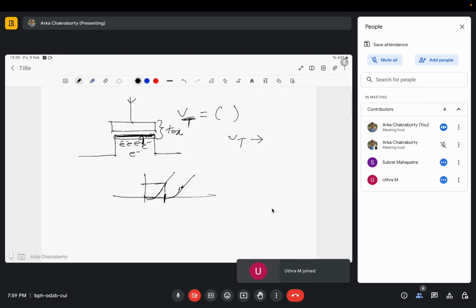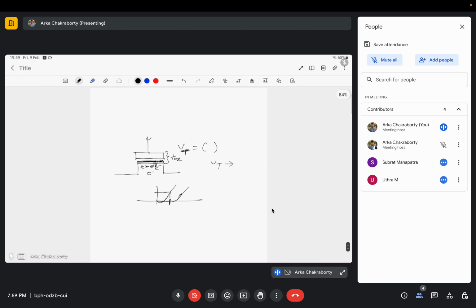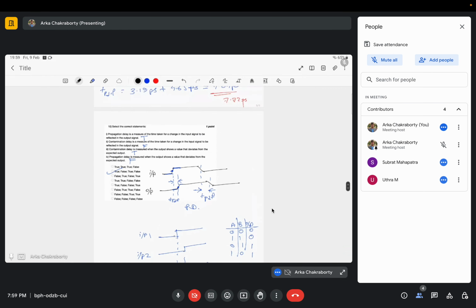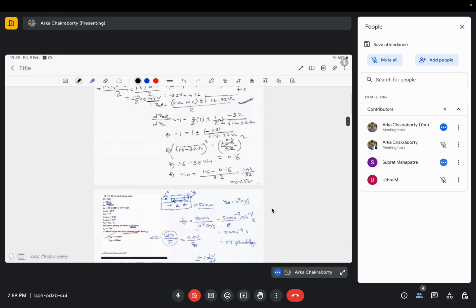Lots of research is going on here, and this is a very interesting field to work upon. Also, due to this tunneling, as electrons are going through here, the quality of the oxide is degraded over time. That's why flash memories in servers, like Google or Facebook servers, have to be replaced every 2 or 3 years, because due to this tunneling the quality of the oxide degrades with time. I went far off from the topic, but as you are interested, I brought this point in front of you. I hope it's clear.